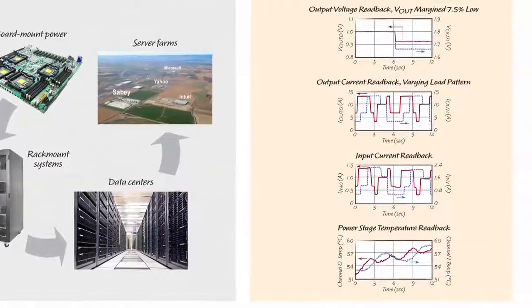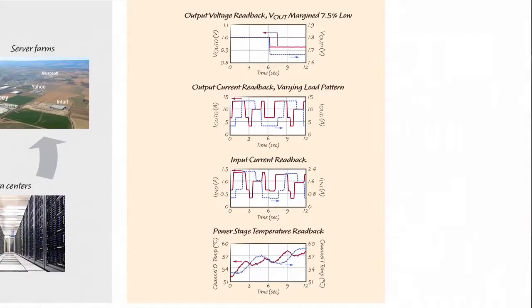PSM products can provide the user with critical power-related data. One can access load current, input current, output voltages, compute power consumption, efficiency, and other power management parameters via a digital bus. This provides the ability to develop predictive analytics, minimize operating costs, and increase reliability for smart energy management.